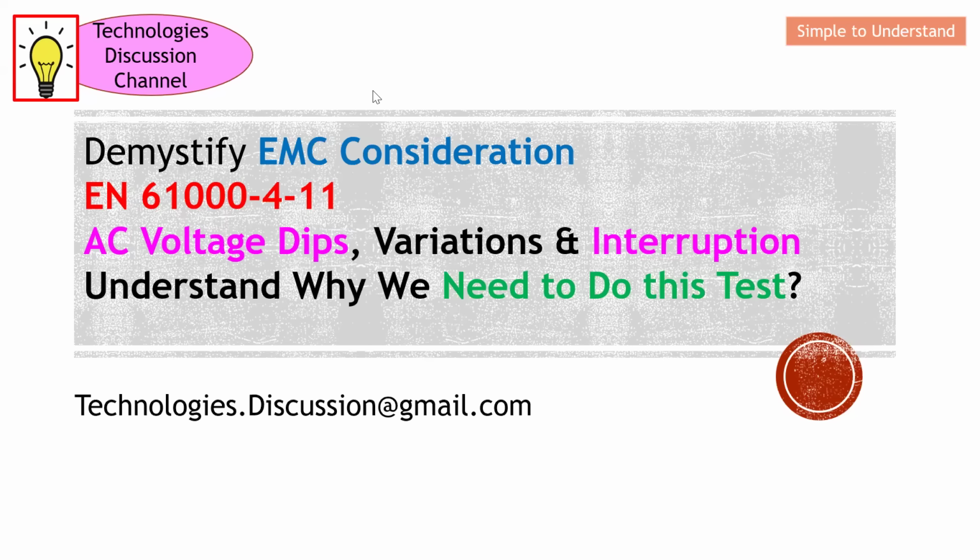For this video, I'd like to continue the discussion on EMC, electromagnetic compatibility. I'd like to focus on one of the EMC standards, which is EN 61000-4-11. Under this standard, we actually have three types of tests. The first one is AC voltage dip, which means that the power is reduced by a certain percentage. Next, we have variation, which means that the power varies. And last but not least, interruption, which means that the power is cut off for a very short time.